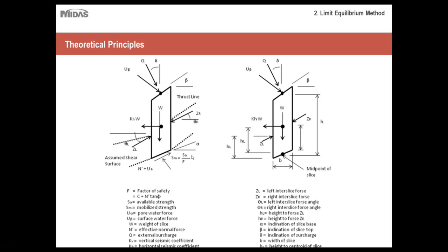Okay, so I won't go into too much detail about all the forces acting on the slices, but keep in mind that the program takes all these forces into account when calculating your factor of safety. For example, the weight of the slice itself, the normal force acting back upon it, shear forces on the bottom of the arc, as well as interslice forces both in the normal and the shear direction, and any external forces acting down upon the slice itself. You can refer to this later when you're studying in your own time, all the different forces that are being applied to your slice.